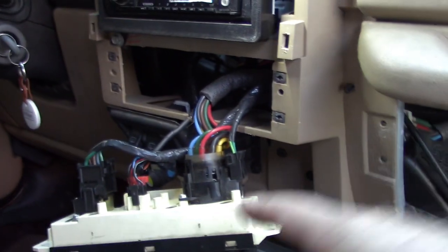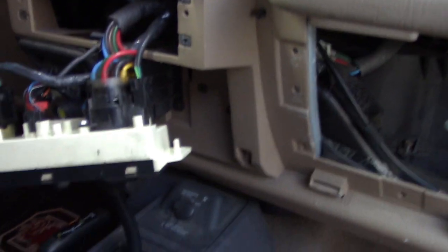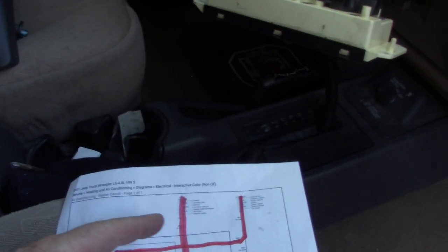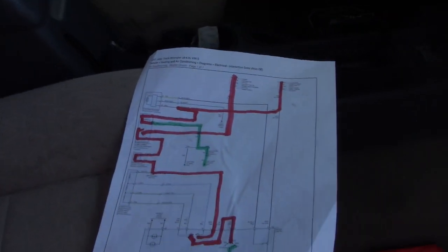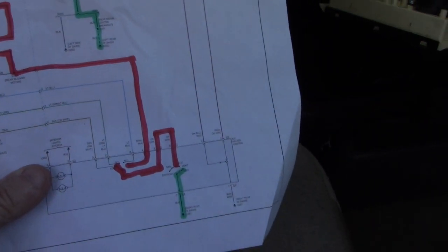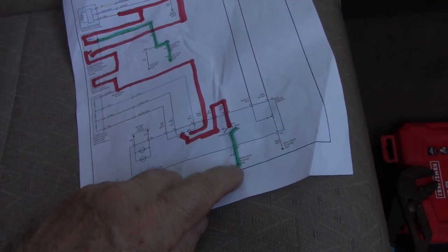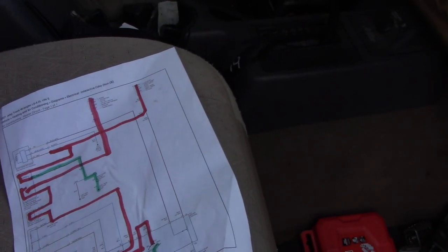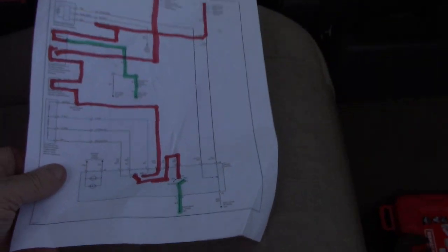Okay, and so pretty easy fix. Hopefully I tried to make it as easy as I could, but kind of going through just a process of elimination. Make sure your fuses are good, and keep following the power until you lose the power. And that's what we did. It was right at the end of the chain where we lost it. It was either the switch itself or the connection of the wire. So all I gotta do is figure out which one it is, and the blower will work again, and I'm sure the owner will be happy.